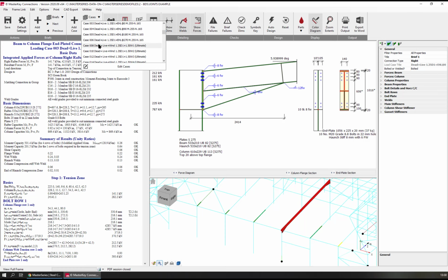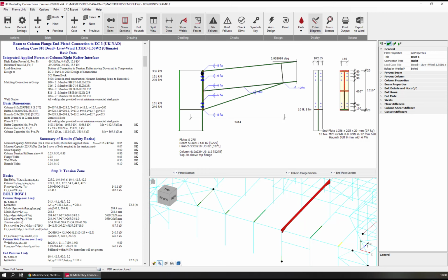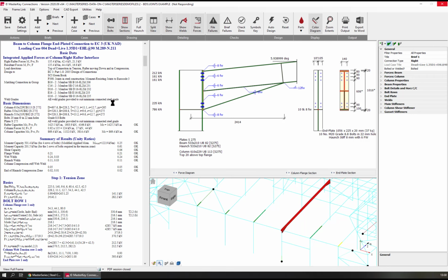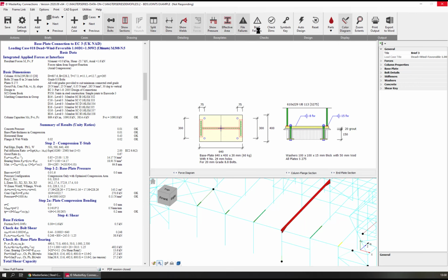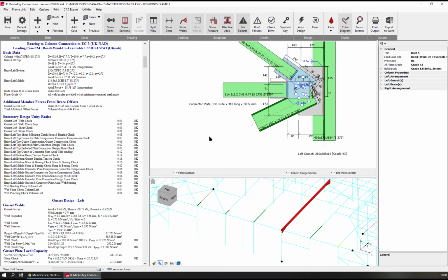So that's the next connection. So it's taking all the loading cases from all 5 of these joints, or the ones on the other side and everything, and pushing them all into that one group and checking them. So what I can do is I can now scan this for failures. And the only thing it will find as a failure is a couple of the connections I thought were compatible. It will tell me that they're not compatible. And I said file rather than brief, so it's doing them for all the joints, which is more fun than I need.